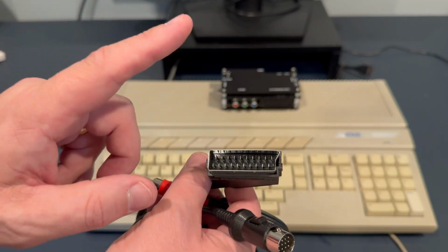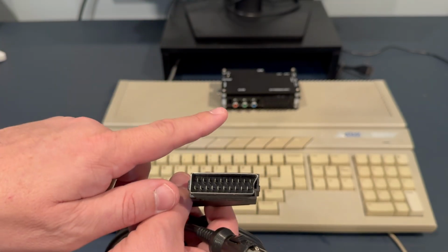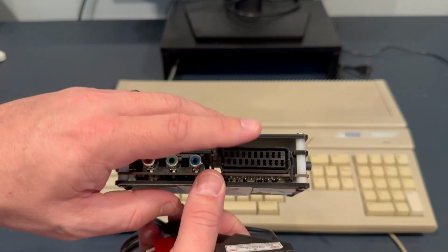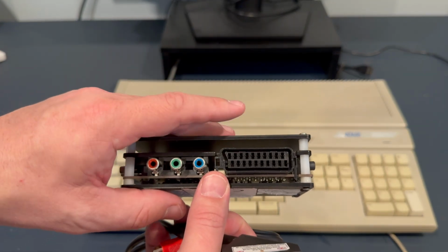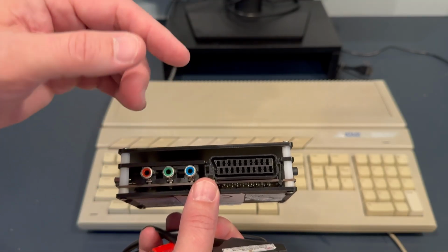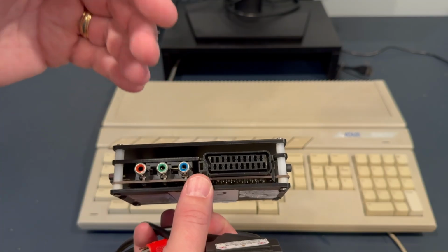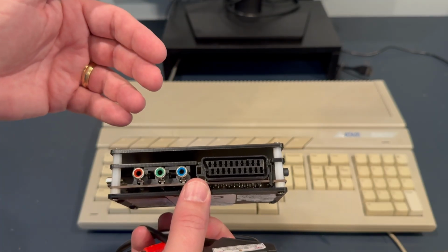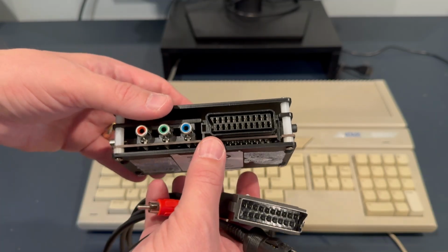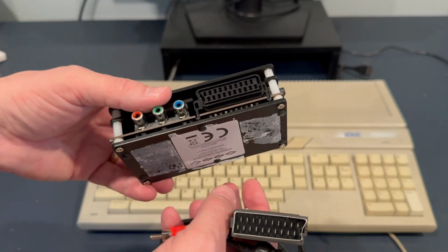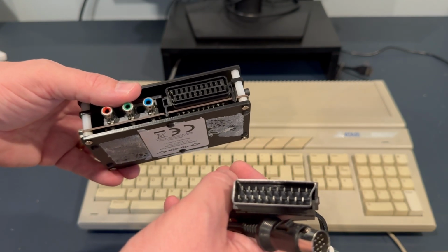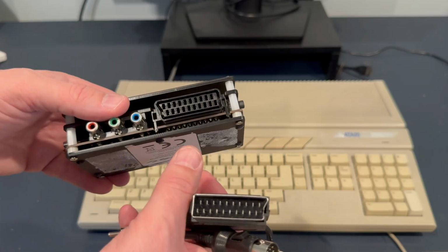You don't necessarily have to connect it to a SCART screen, but you can find many upscalers. Again, the OSSC is one of those kinds of upscalers. While VGA to HDMI upscalers are more problematic because they're expecting a standard VGA signal, SCART to HDMI upscalers are expecting a standard SCART signal, which the Atari ST in general will output. I'll get into the nuances of it in just a minute.